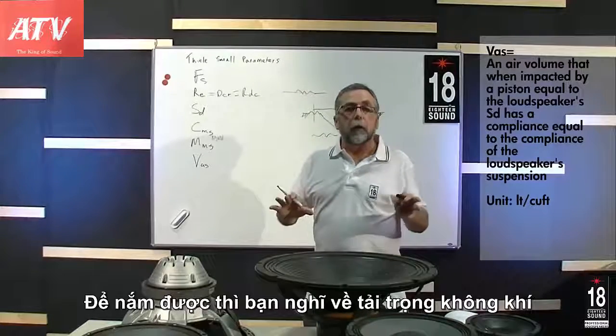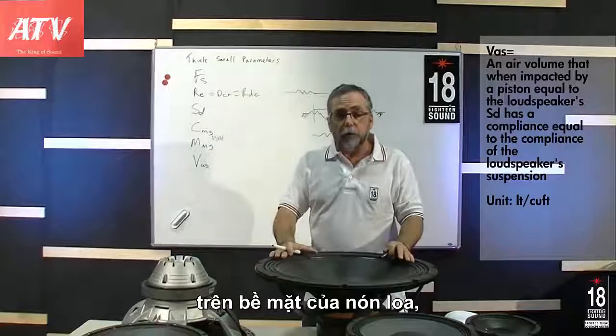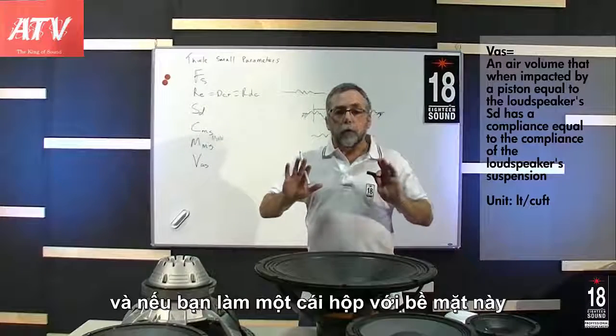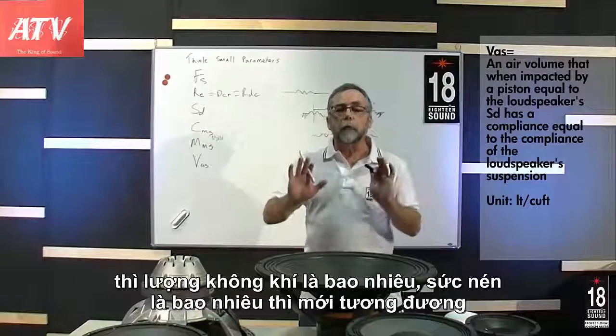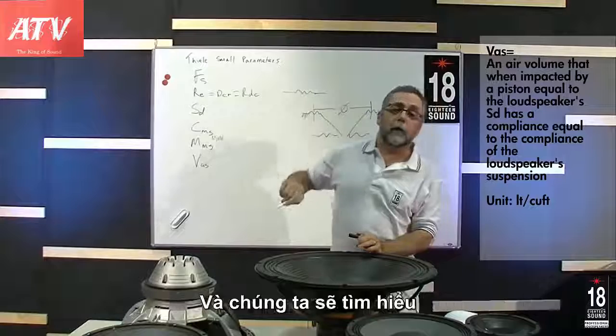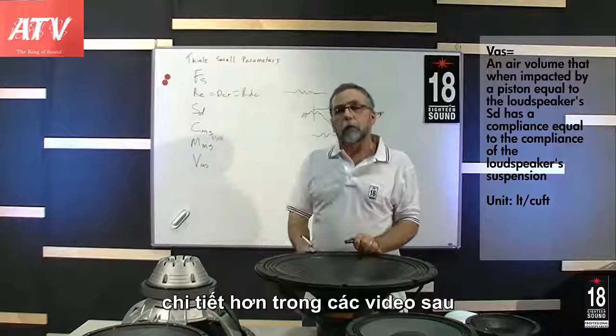Then VAS is known as the equivalent volume for the spring of the compliance. And this is made up, if you think of the air load on the surface of the cone, and if you made a box with this surface and you had created a spring to push back, how much air, how much compression would equal the compliance of the moving parts of the loudspeaker. And we'll get into more details on these later on in other videos.